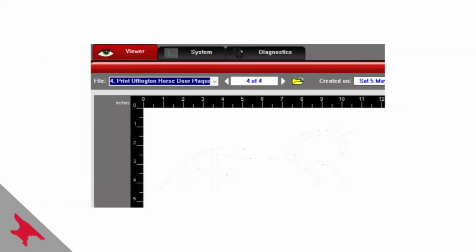The ULS program on the laser cutter is a little bit different again. With the laser, the line color and thickness matter because the software interprets different colors as instructions to do different actions with the laser. With the standard settings on our laser, red lines are for cutting all the way through the material, blue lines are for engraving on the line that you drew, and black lines and shapes are for raster engraving.